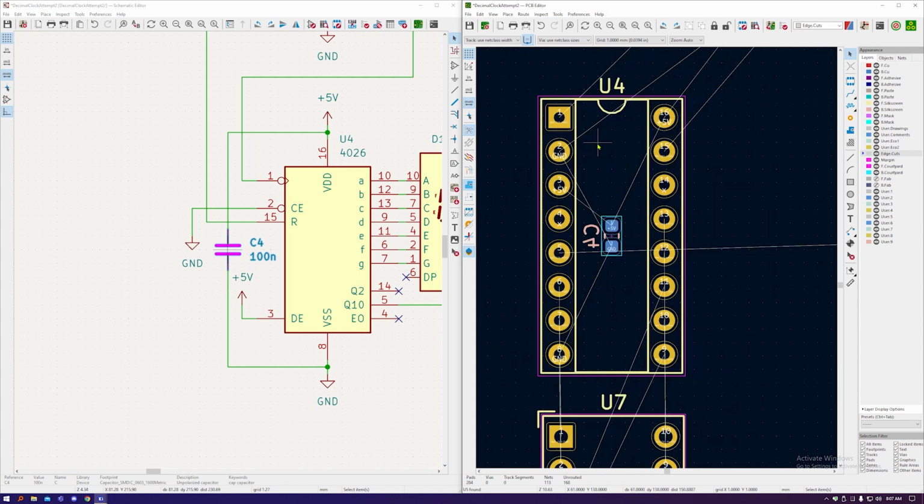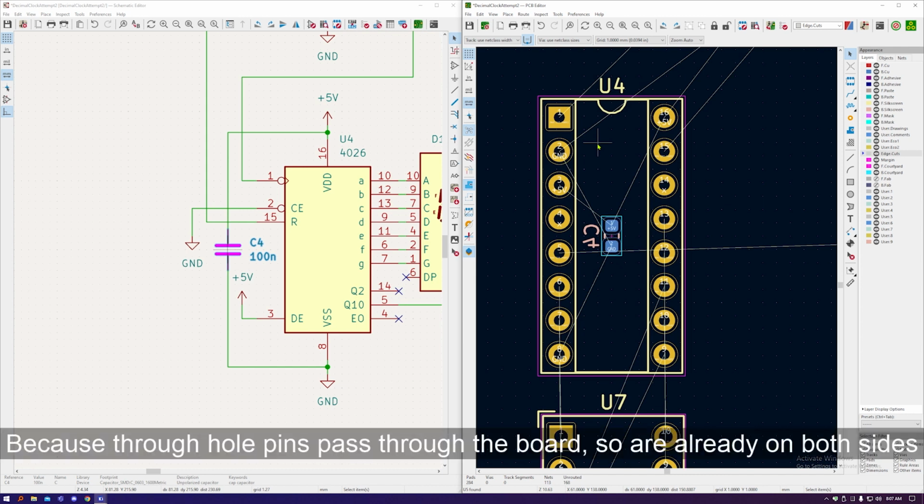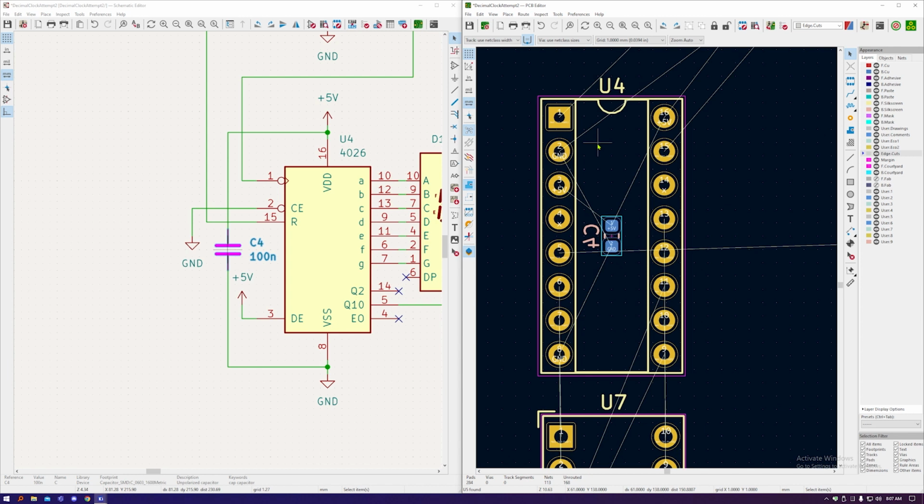And most boards nowadays are at least 2 layers, so it's a good thing to get used to, making the most of the fact that you can put components on the back. If you're manufacturing them, if you're assembling them yourself, that's not really a problem at all. As long as it's surface mount, you can't really do through-hole things on both sides. But if you're paying to get the board assembled, often they'll charge quite a lot more for double-sided assembly, so that's when you'd then try and keep everything on one side. But we're better than that, we can make our boards ourselves.